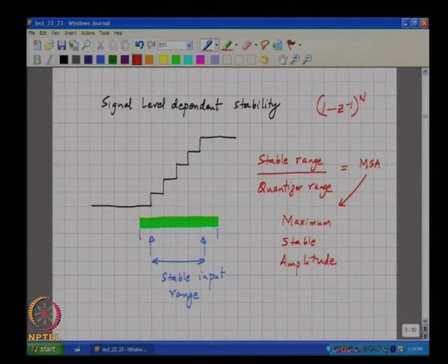The shaped quantization noise and all these assumptions make sense when you are starting from within the middle of the quantizer and keep going up, because as long as you do not hit the saturation limits, the quantizer can be pretty much thought of as an additive noise source.